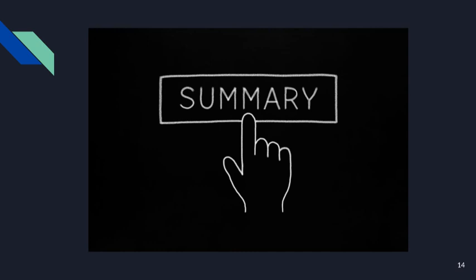Moving on to the resistance change principle, we found that this is used in a wide range of devices for temperature measurement, resistance thermometers and thermistors, as well as displacement measurement, strain gauges, and piezoresistive sensors. We also noted that some moisture meters work on the resistance variation principle. We then looked at sensors that use the magnetic phenomena of inductance, reluctance, and eddy currents.